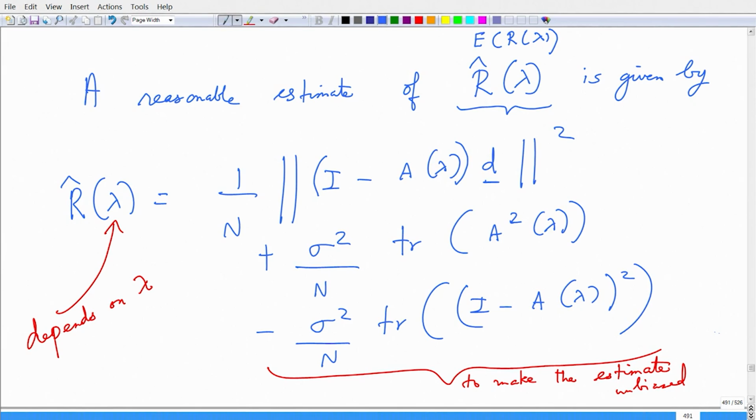You may question at this stage, how do I choose that lambda? Recall, there is a connection between lambda and the influence matrix that you have, right. The influence matrix entries are dependent on lambda. So, therefore, if you directly plug in the parameters of the influence matrix into the Tikhonov functional and solve for the entries of the influence matrix, you in a way have figured out what should be the parameters that optimize the regularized cost.